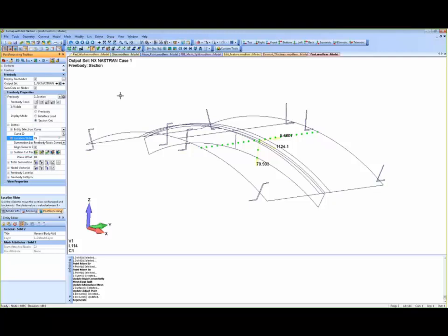So if you take those loads and maybe put them into Excel to see how they match your hand calculations, you can export those sums at individual percentage offsets of your plane. You can export it using the list current free body summation to the data table, or you can export it down here to the messages window as well.